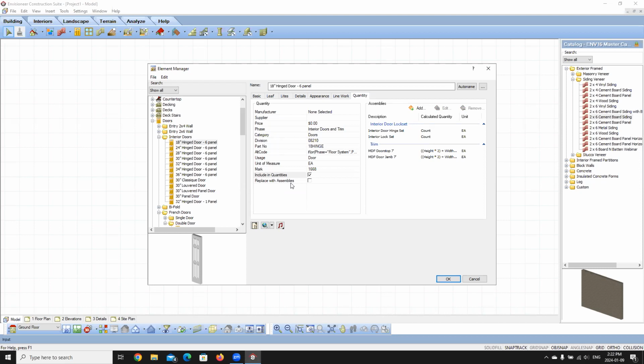So we're going to take advantage of this and look at it in actual practice here. Let's say you want to add a fence to your design and you want to report the number of rails, posts, and boards that will be used. To achieve this, you would need to create a formula for each of these assembly items that includes the variables for the spacing of the posts, the overall length of the fence, and a rounding factor in case the overall length includes a decimal portion.